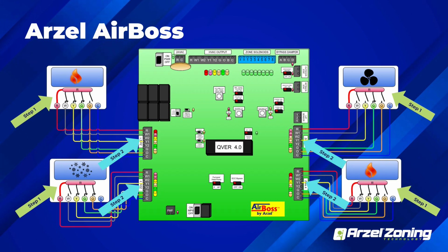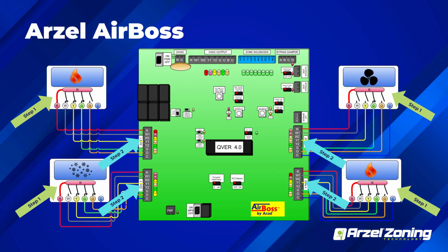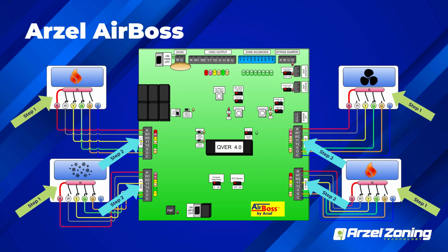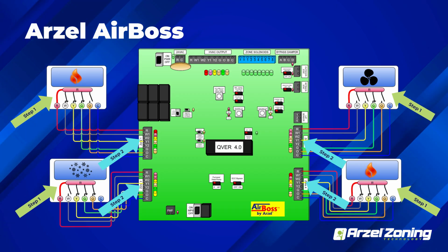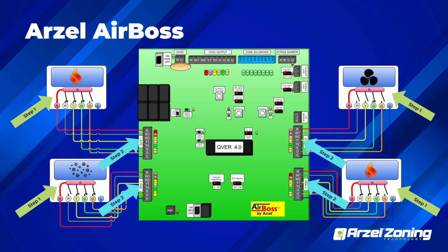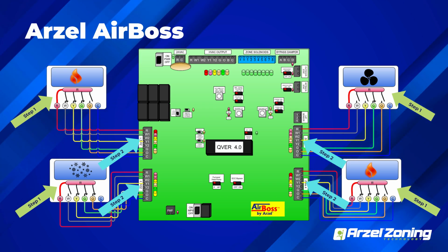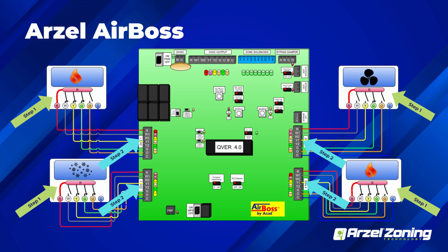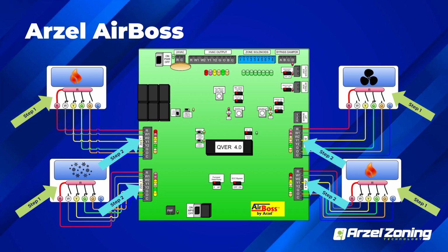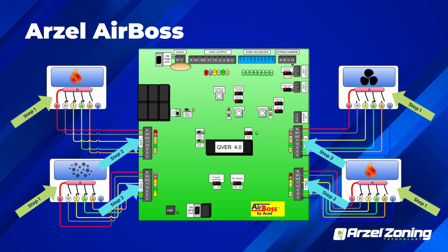And as a coordinator, it determines what takes priority: heating, cooling, or fan. Doesn't matter what panel of ours you have, fan is always the least priority. So we pick between heating or cooling based on your operation. If your thermostat is calling for heat and the other thermostat is calling for cooling, you can set a priority between heating and cooling calls and it will serve that priority.